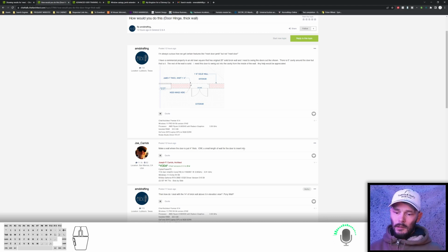And you can even control your layer stack, especially if you're working over in the UK. This is a really common thing to see: you've got a really thick masonry assembly for your walls, and then on top of that, you might have a framing assembly, and you might be recessing a door into the inner portion of the assembly. So you can do that with multiple walls and just butt them together. And if you're using tab input, you're going to place those walls in a way that they butt perfectly and make sure that there's no spaces in between. Use your temporary dimensions to set that distance between.